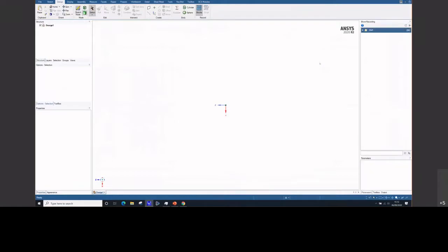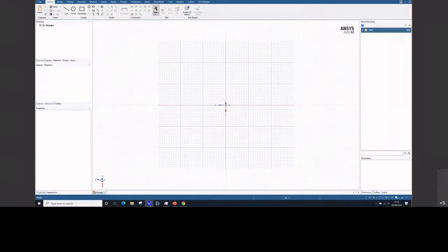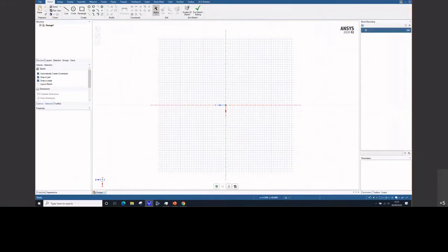So we can see a panel on our right hand side here, and from there we'll click sketch mode, and we'll choose an axis to sketch off. I'm just going to choose the Y, and that'll just drop a sketch onto that Y axis. I'm just going to go into a plan view. Always nice to sketch in a plan view. And literally, just going to start with a simple rectangle.